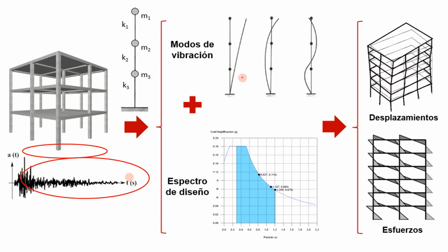In this case, we can use dynamic and static analysis, and also consider the rigid diaphragm. I forgot to tell you that. We also assume first-order elastic linear analysis, and in the software we can use the accelerogram to get the frequency, the period, and the acceleration.